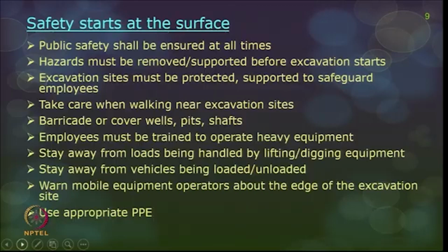So, you should be very careful when you are walking near excavation sites, and always try to barricade or cover any wells, pits or shafts, and the employees must be trained to operate any equipment. As a general precaution, when any lifting or digging equipment is operating, don't go near it. Stay away from the loads and stay away from vehicles which are loading and unloading.